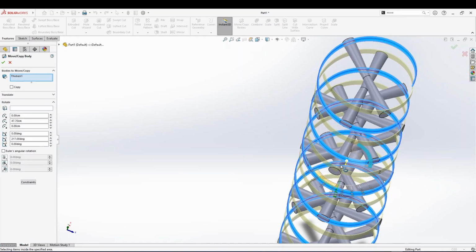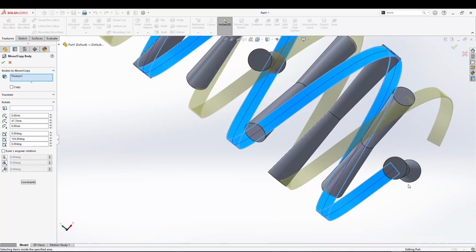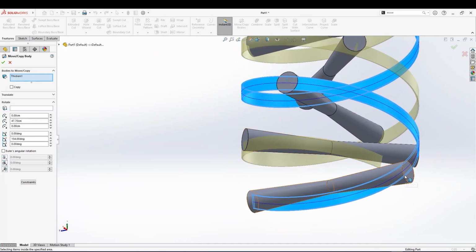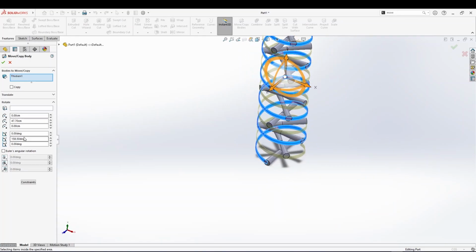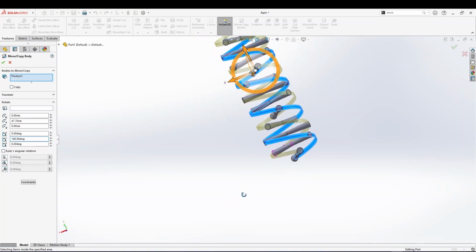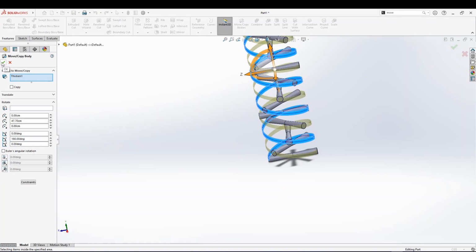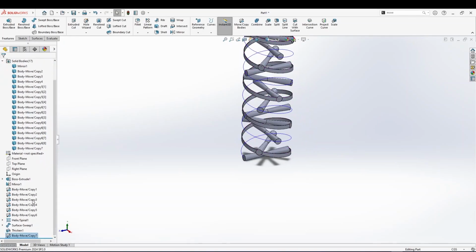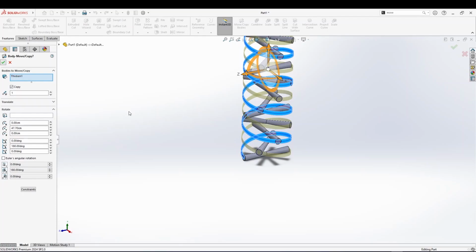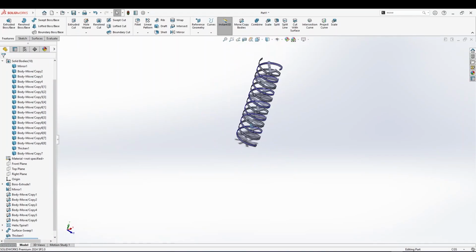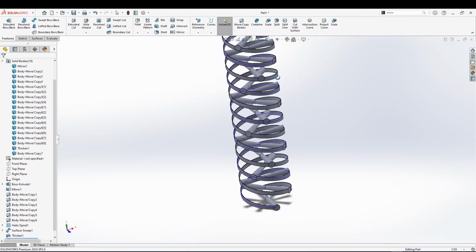Just rotate it here, and I want it to rotate in a way that this one connects with this one. Okay, it will be an opposite one, and as I rotate, I pay attention that this angle is changing, so let's just make it 180, because I want it to be opposite. Okay, looks good. And again we apply it, and again we forgot the check mark. You see the spiral moved, and we have the initial spiral just rotated, but we actually want to have it as a copy, right? Okay, so it's our initial DNA structure, and it already doesn't look right to me.